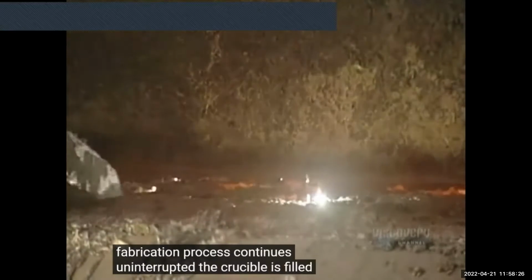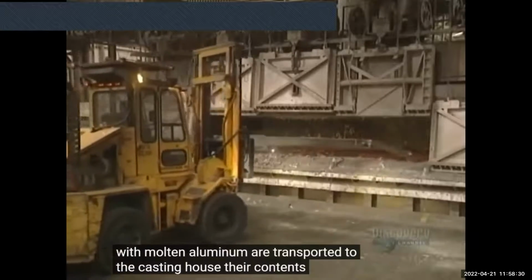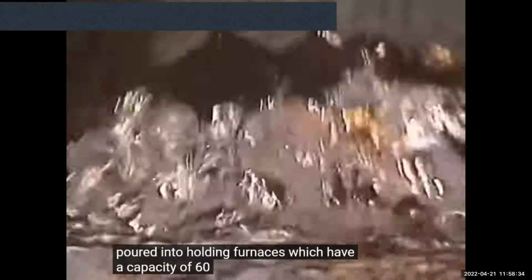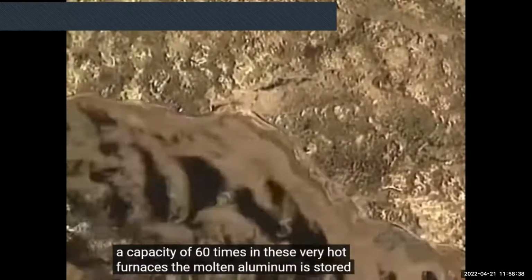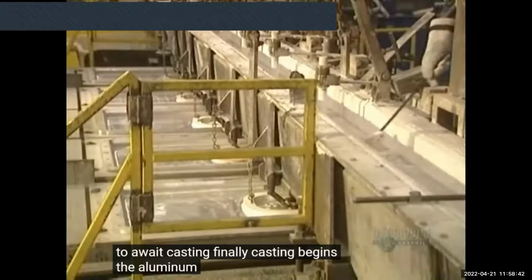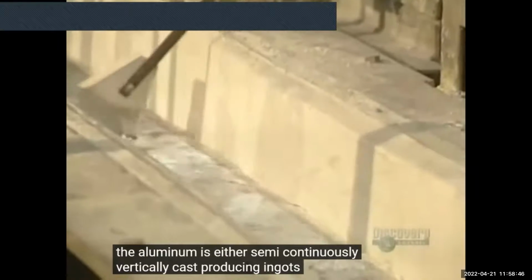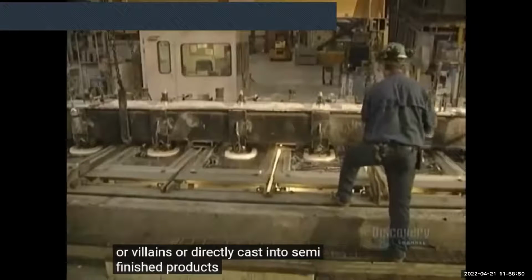The crucibles filled with molten aluminum are transported to the casting house. Their contents are poured into holding furnaces which have a capacity of 60 tons. In these very hot furnaces, the molten aluminum is stored to await casting. Finally, casting begins. The aluminum is either semi-continuously vertically cast, producing ingots, sheets, or billets, or directly cast into semi-finished products.